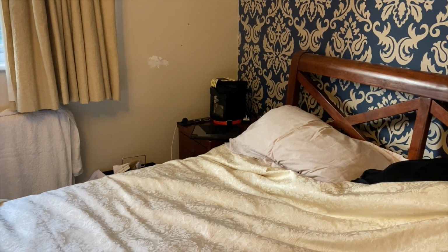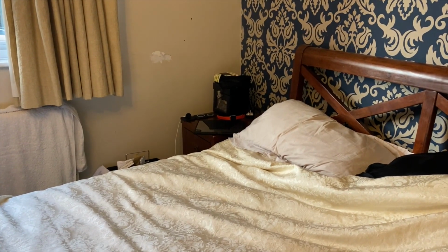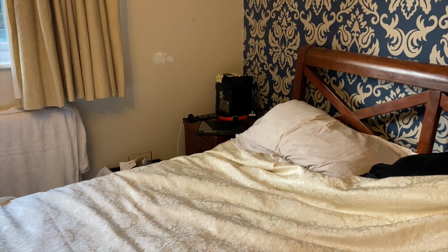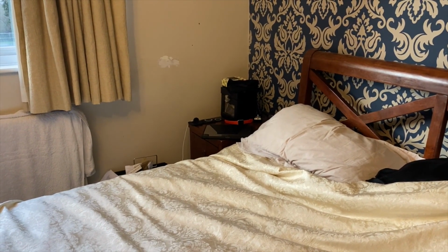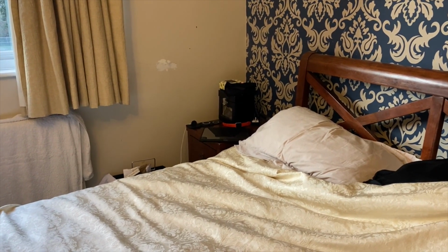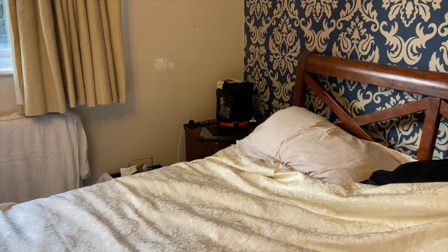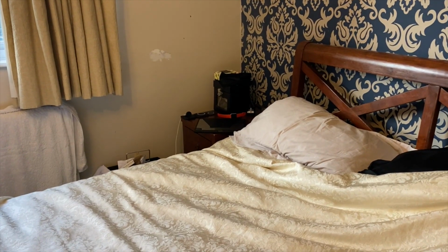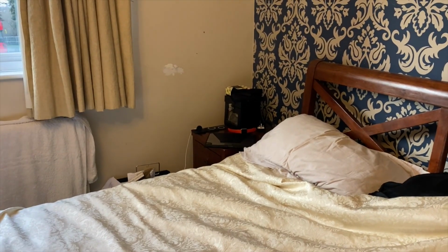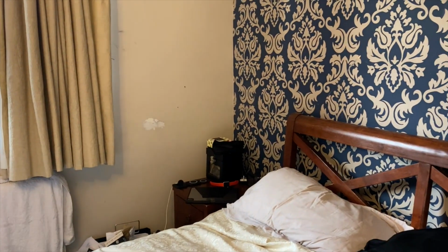One is that the cracks are very thin, and you can use an acrylic caulk. The other thing is you need to use an impermeable paint because it's an impermeable render, so the water isn't getting through. Otherwise, you can end up hiding a crack, and it still absorbs water, but it's hidden. Dulux do an impermeable, and Zinsser do, and just look for the outside paint, outdoor paint. Yeah, exterior paint, external masonry paint.